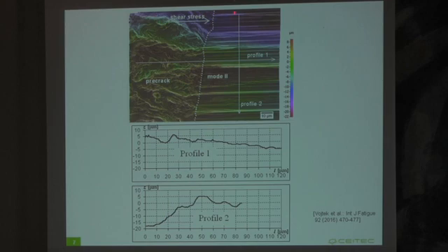Second, when we look at this profile perpendicular to the growth direction, you can see here, we found that actually these lines are parallel to the local crack propagation direction, and they originate on local irregularities of the pre-crack front in 3 dimensions. So this is important for the next analysis of Mode 3 cracks.